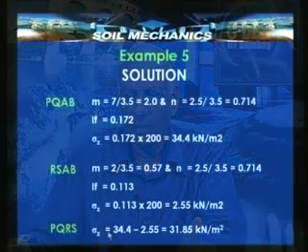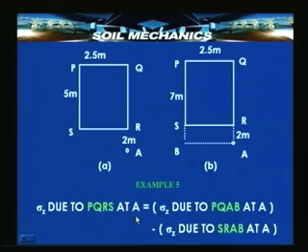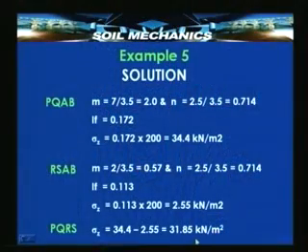So, also with PQRS, PQRS has a stress value sigma z corresponding to a value of m and n equal to 2 and 2 upon the depth, which is also 2, and that will give us influence coefficient for that smaller area, and that needs to be added, and then we can get PQRS algebraically added, and we get PQRS.